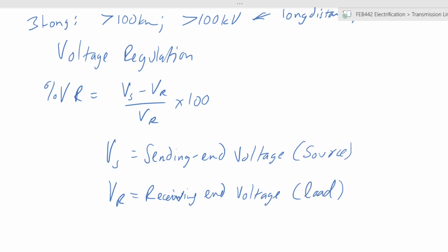So at the consumer's position or at the transformer in terms of a substation, wherever the destination of your transmission line is. So this measures how much drop in voltage you experience by passing voltage or passing power through a specific transmission line. So it will depend on many things. If you have a long distance cable, for example, the impedance that you will get due to resistance, inductance, and capacitance has an effect. The inductance and capacitance of the transmission line will change the power factor.